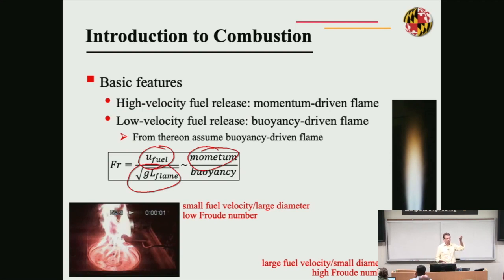And the fact that we get flow velocities of meters per second scale is due to the acceleration of buoyancy. So we are in the regime where the Froude number is very low, and we are dominated by buoyancy in fires.